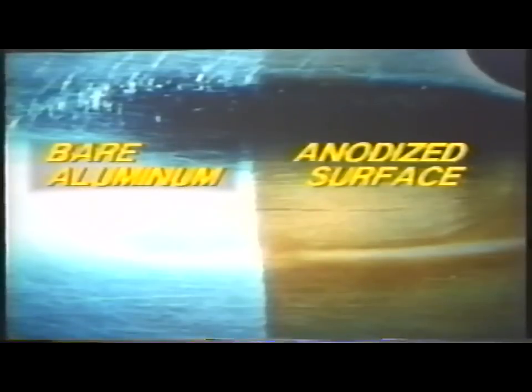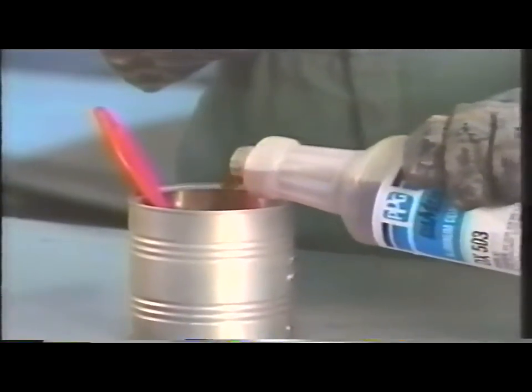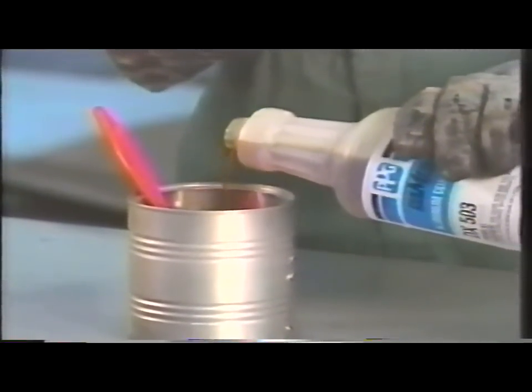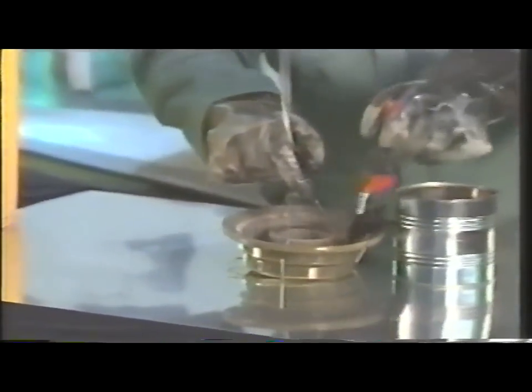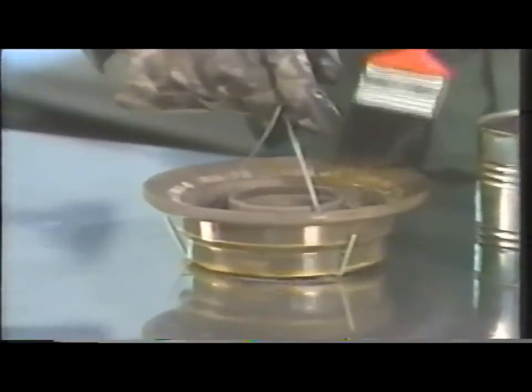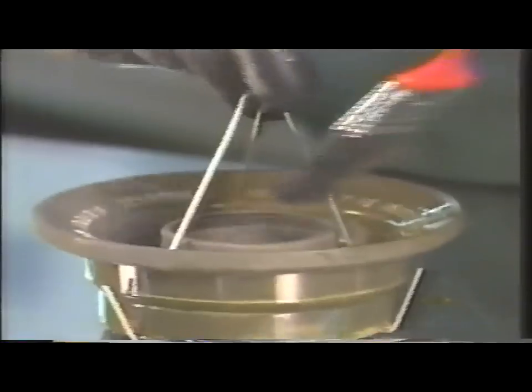Many non-clad aluminum alloys used in aircraft are anodized prior to construction. Anodizing creates an aluminum oxide surface barrier which is naturally protective, adding to the alloy's natural oxide film. You must restore the anodizing coating to rework surfaces. After cleaning, a chemical conversion coating such as chromic acid or Alodine should be applied to inhibit corrosion and provide a suitable surface for painting.